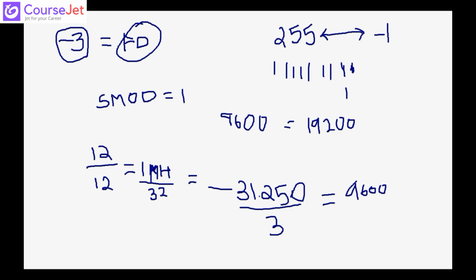The next bit is SM2, which is for multiprocessor communication, so it becomes 0. The fourth bit is receive enable, which we are making 1. Next are TB8, RB8, transmit interrupt, receive interrupt. So this becomes 0x50. Fine.